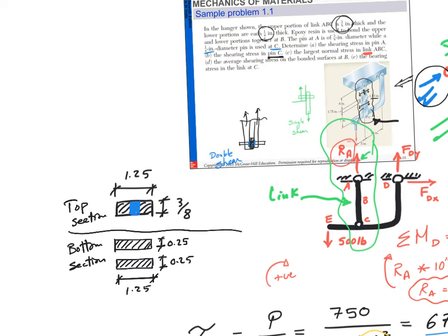Right? And this guy also has a hole somewhere, one at pin A and one at pin C. Do you understand? So the critical place that holds the highest stress is the place where the holes are, which we sometimes call, when you go to steel design, you probably are taking steel now, area net. You guys taking steel or you already took it? Exactly. Area gross and area net. What's the difference? Take the holes out. If you take the holes out, you get more critical areas.